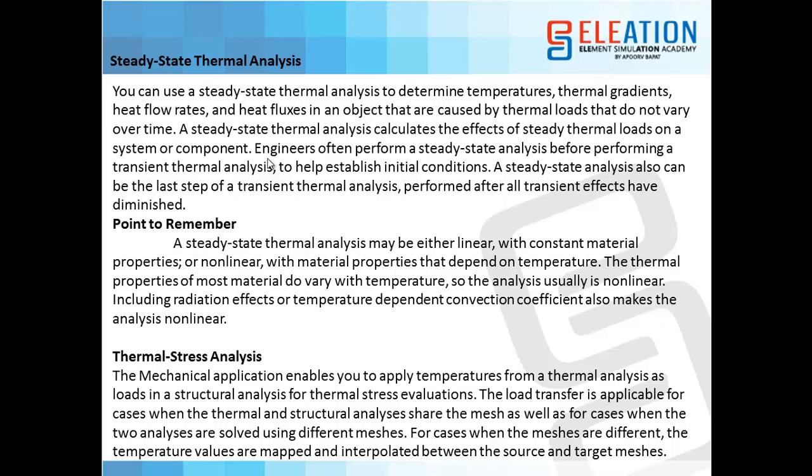So we can perform two types of analysis in thermal. One where we consider conduction and convection, and the other where we see the thermal stresses, that is, at the temperature, what stresses are generated or what deformation happens. So in one, we see how the temperature is moving from one component to another and how the heat dissipation is taking place. And in the other type of thermal analysis, we will see at a particular temperature what is the maximum stress and deformation coming on that particular component.